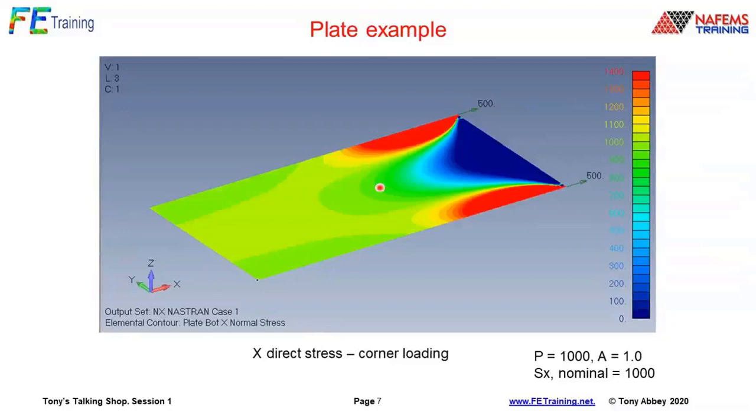Now, I've played some variations on this. I've said, well, let's put corner loads on, or a center load. So really trying to emphasize the point that whatever happens in our target zone, it doesn't really care too much what the loading form is there on that right-hand edge. I've split the load here corner to corner. You can see the blue here, and the way I've chosen to represent the stress is that blue is zero stress. So you can see that stress diffusion and stress flow.